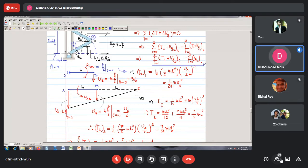Correct? So member 1's kinetic energy will be, since it is turning about point O, half times 1/3 mv square into the angular velocity of this link squared. If this end's velocity is Va by 2, I can divide it by B to get the omega of this link in terms of Va, and that is Va by 2B whole square.